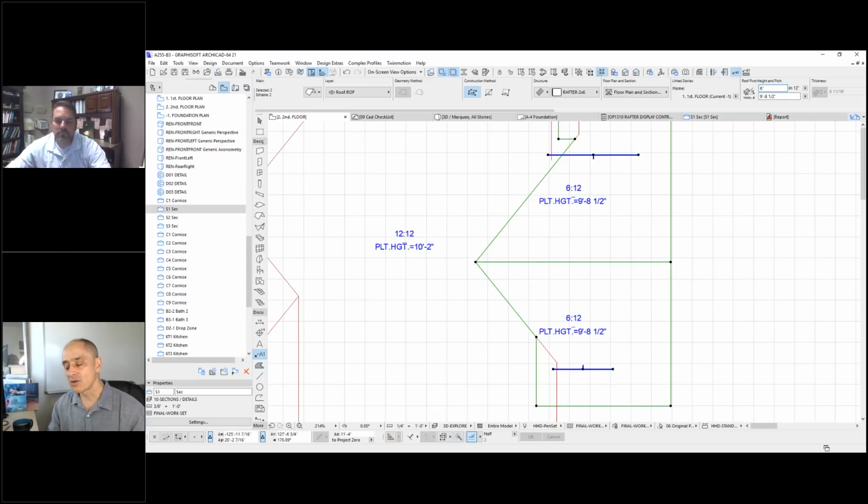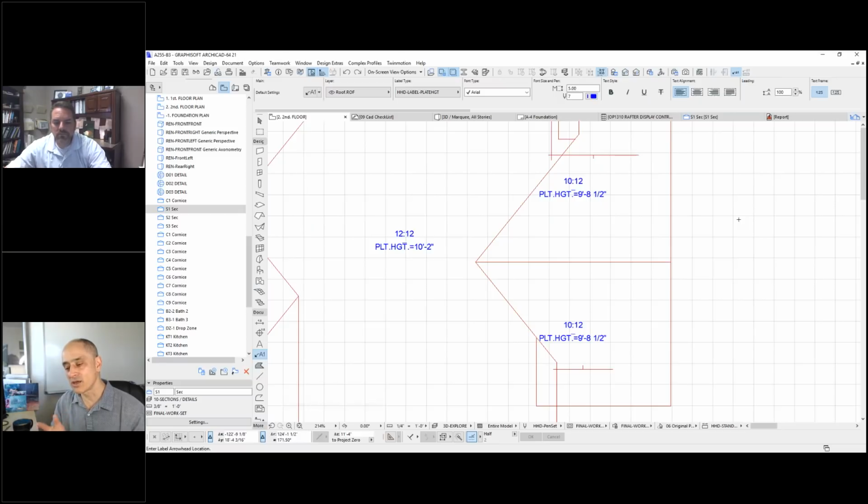When you take it out to the face of the building or beyond with an overhang, the natural fascia of the element is whatever that works out to vertically. When you're designing something for final, you might put a board on the edge that makes the fascia a different dimension.